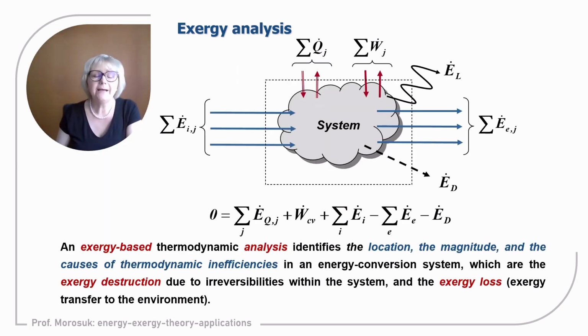Let us repeat that thanks to exergy analysis, we can identify the location, magnitude, and causes of thermodynamic inefficiencies within an energy conversion system. We can apply exergy analysis on the component level, but also on the level of the energy conversion system, regardless of how complex it is. And very important, inefficiencies will be associated for us with the value of exergy destruction, which describes the irreversibilities within the system, and the term of exergy losses, which means exergy transfer to the environment.